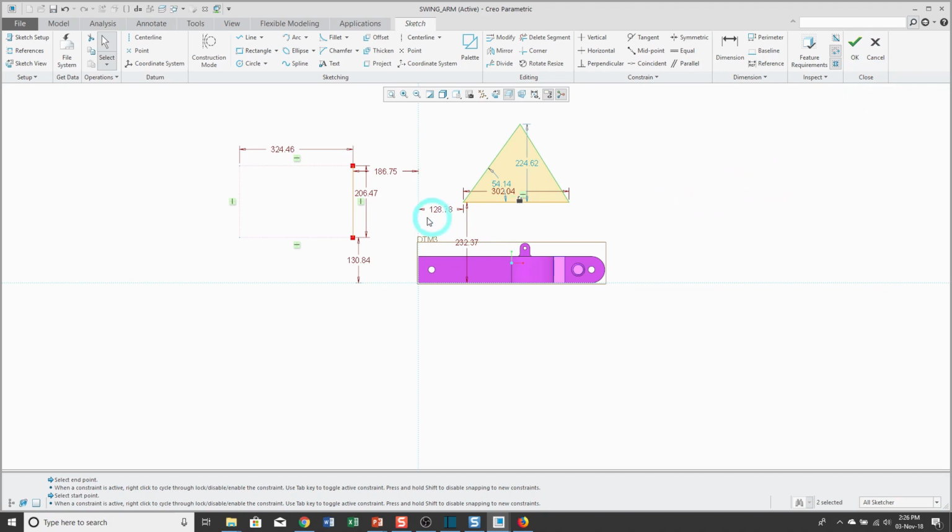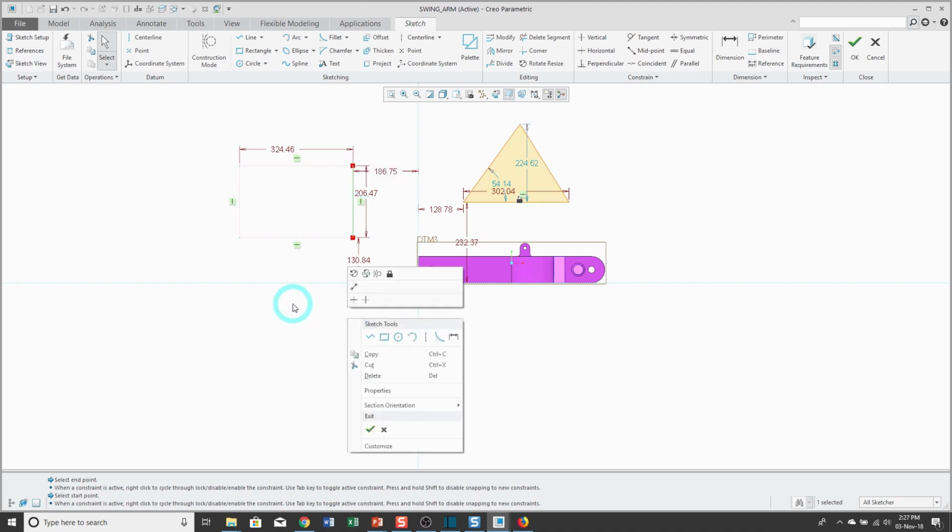In Creo 4.0 and later, when you select an entity, you're going to get a mini toolbar with different icons. And if you hold down the right mouse button, you'll get an additional what's called an asynchronous menu. Everyone just calls it the right mouse button menu with commands as well. And so this is a quick and easy way of getting to different entities and reducing the amount of mouse travel that you are doing. All right, so that is the interface in sketch mode.